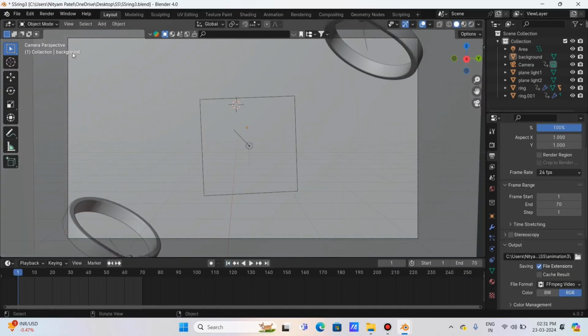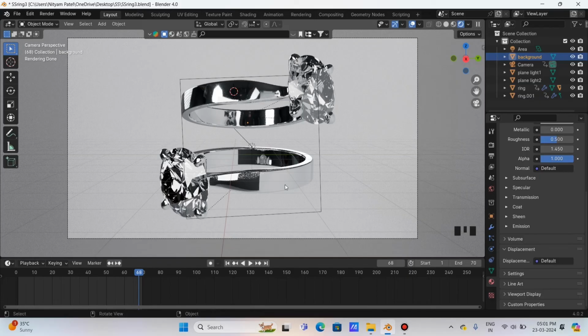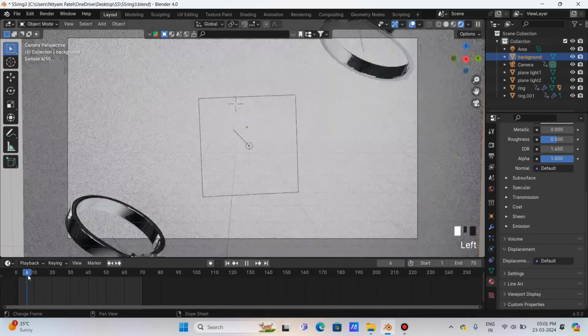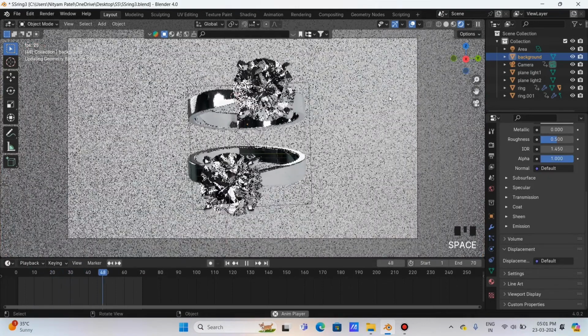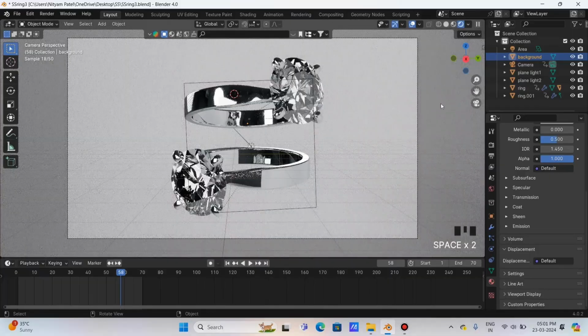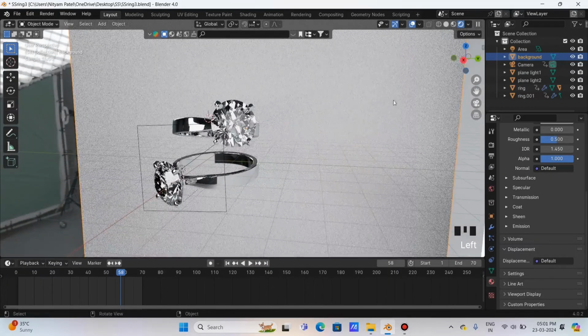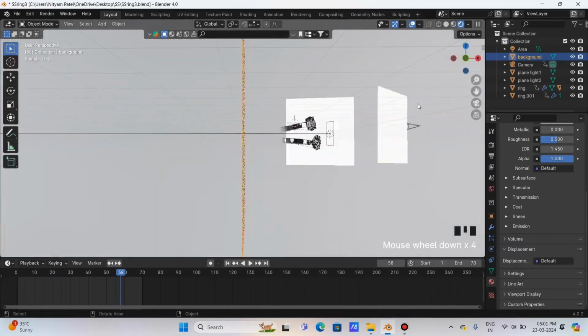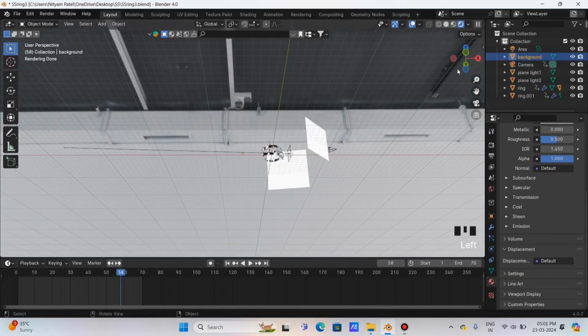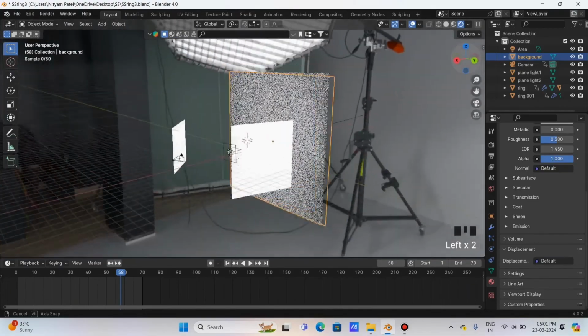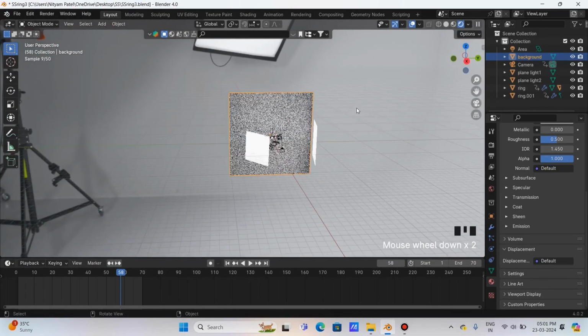I go to the viewport at the first frame and render the animation. If you find a problem, then solve it. At around frame 2 to 3 I find a very blurry white shadow. Here you can see that I find this problem, but our background has no glossy effect. So I do some searching and found the problem, which is the HDRI. Our right side of the HDRI wall is too white, so that is the reflection of the wall.